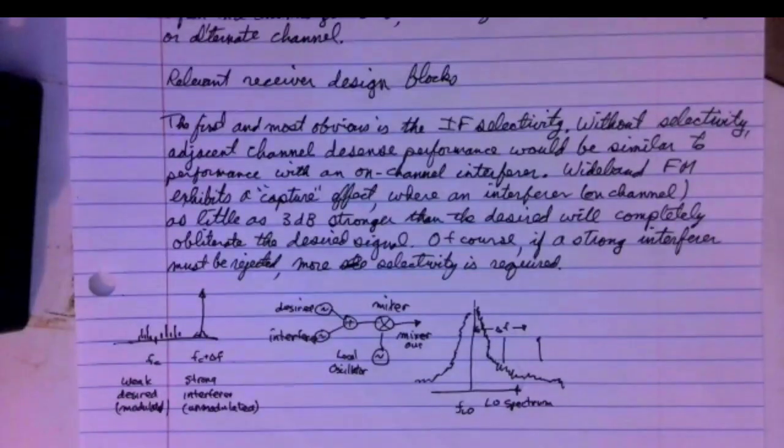The minus side is that aircraft communications do not use FM specifically for that reason, because with an AM receiver, if you have two people on the same frequency at the same time, you get some indication that your communication is garbled and something was wrong.